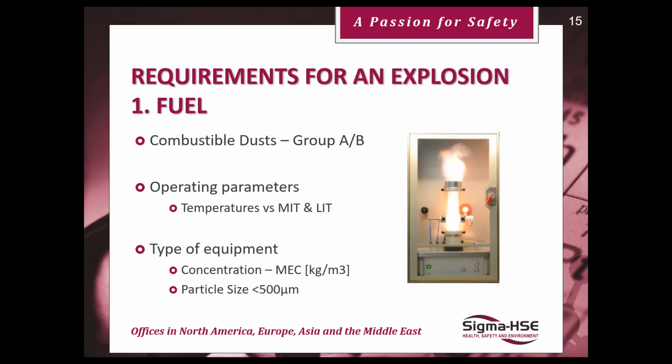When we're dealing with dust, it's pretty similar. The first thing we need to know is whether or not we have a combustible dust, whether or not that dust will react with oxygen. In a sense, a good chemist should be able to look at the substance and its formula and work out whether or not it's capable of being oxidized with oxygen.